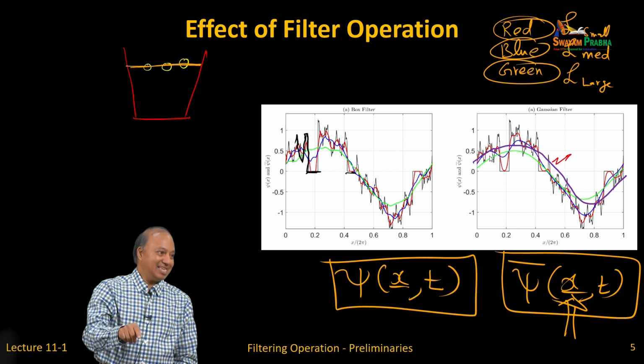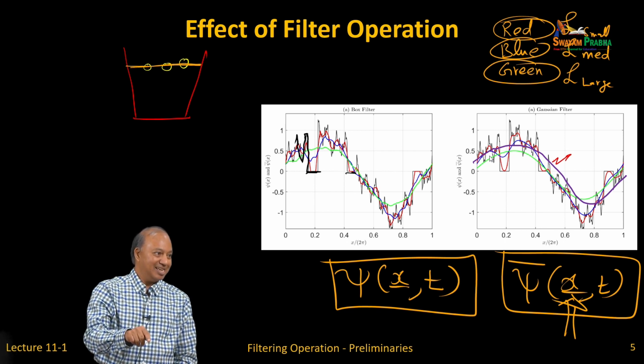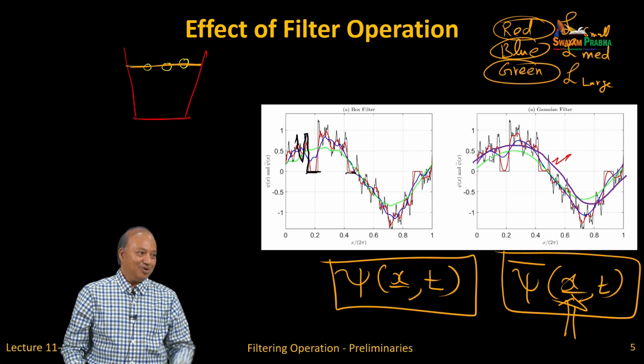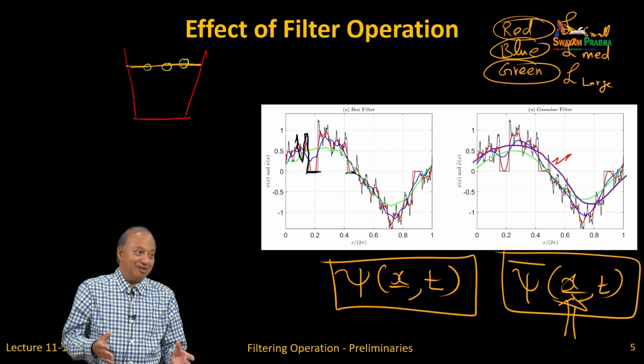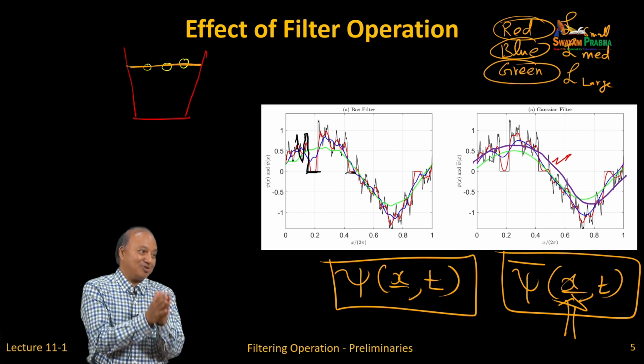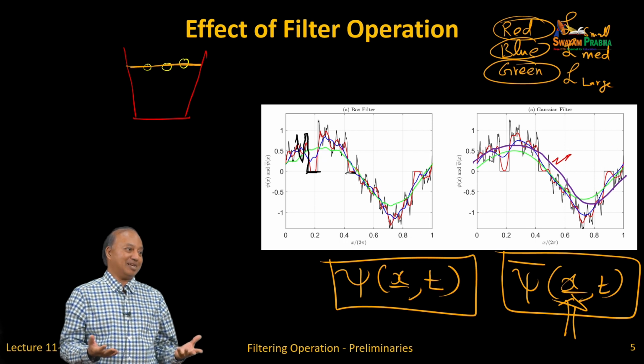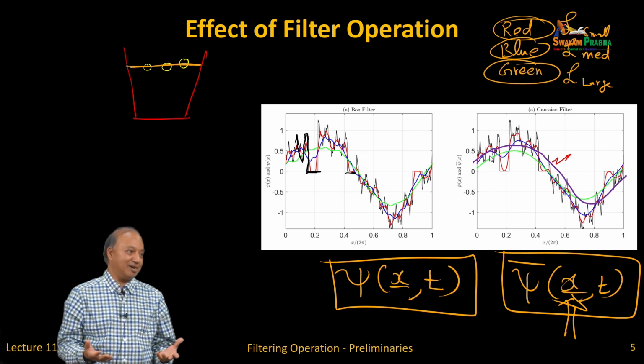It does not make any sense to do Euler-Lagrange simulation so big. But in your case, you have been tough luck, because if you have shock, okay, to resolve the shock you must have small grid, but on the other hand particles may be big. So, compressible flows are very hard problems, okay.